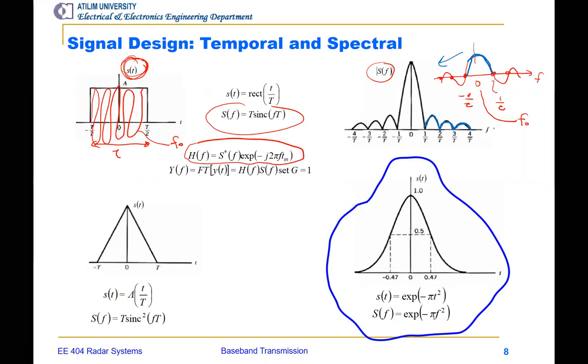Their amplitudes decay with the frequency, but it goes to infinity, okay? Which is a problem, because if we are interested in the range of the frequencies of the signal, in order to recover the signal, we have to design a filter, or we have to design a receiver which covers all the frequency components in this range, which is impossible as the signal spectrum goes to infinity. Then we have to do something here.